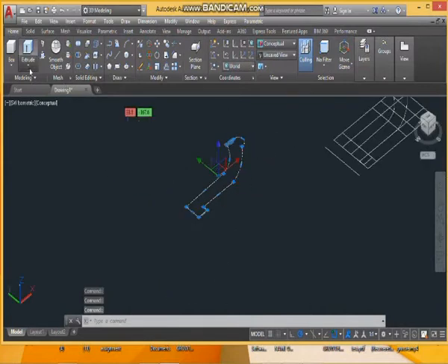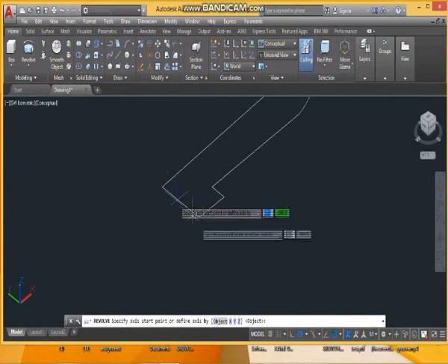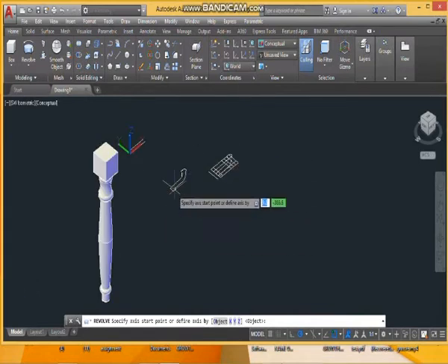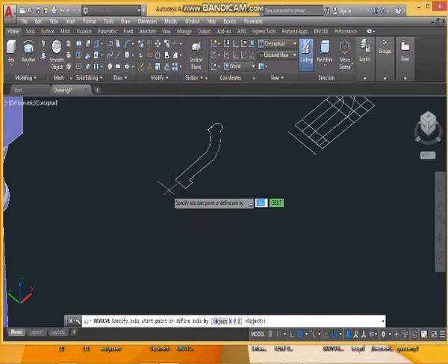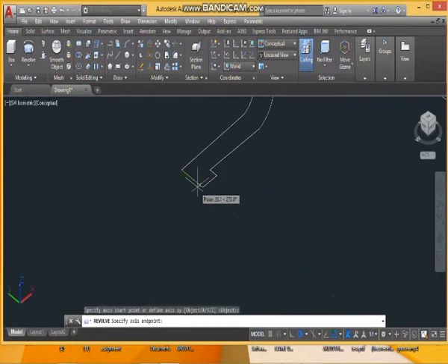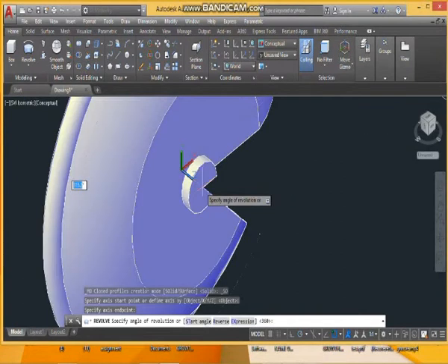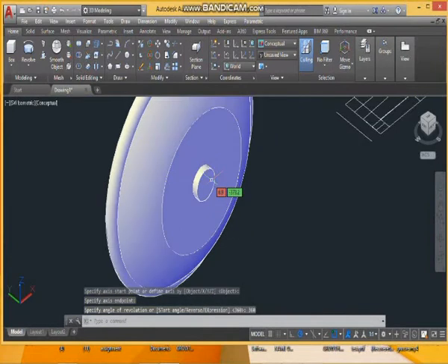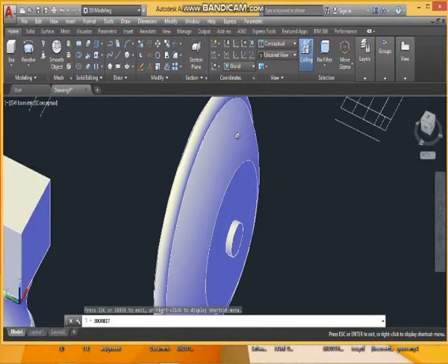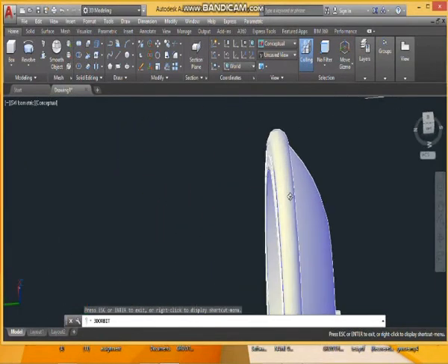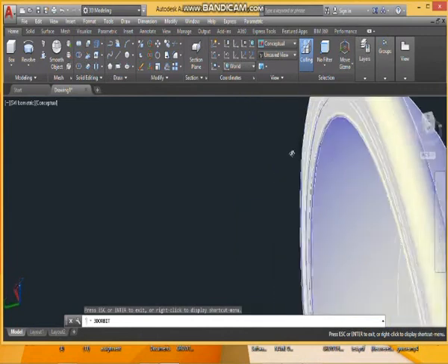and we pick under the extrusion tool the revolution tool, and we identify our axis of rotation so that we'll come out with something round. We'll pick, and then we'll click to select an angle of rotation which is 360 degrees, and automatically our plate is realized. Do this for any other round object you want to realize in AutoCAD. It is about the same procedure.